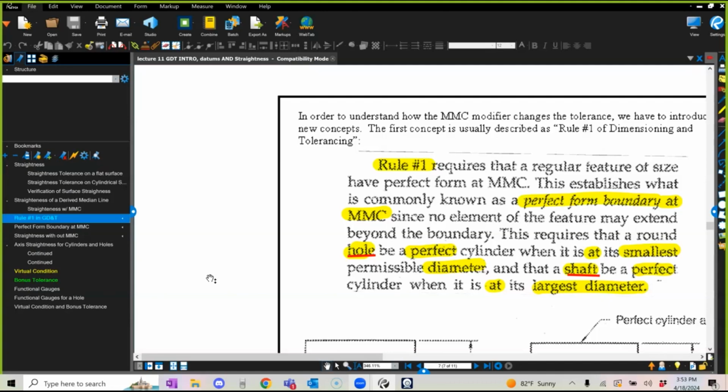And that envelope has a certain size. The biggest that this envelope is going to be is your maximum material condition. Let's think about your part, which is going to be this green sleeve, can be small and big. You have your upper limit and your lower limit, right? I'm going to make this envelope the biggest it can get, the maximum material condition.